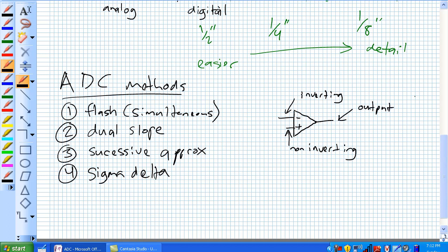Okay, so the op-amp, without all the great stuff in EET 221 and 222, can be summed up as follows. It is a magic device. Don't you wish you just had that word when you went into 221 and 222 and could just forget all the rest? It is a magic device that holds the inverting and non-inverting inputs at the same potential.